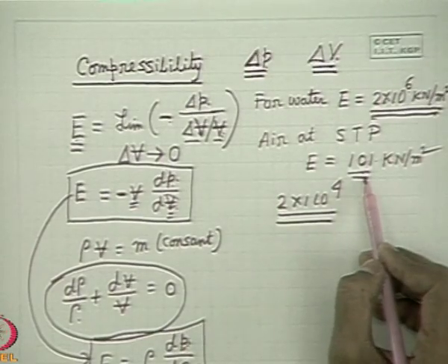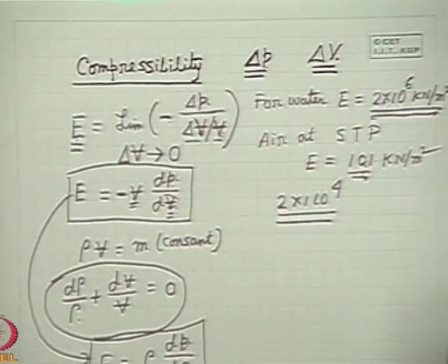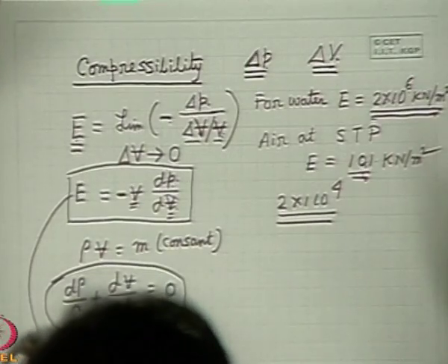So, the less the bulk modulus of elasticity, the more the compressibility of the substance. Well, it's clear. Now, a very interesting question comes in engineering applications. We define the fluid by the compressibility parameter, we apply the pressure and find the change of volume and density, and we find the value of the bulk modulus of elasticity. Qualitatively, we see that the change is very small even with a very high pressure, so it is less compressible, it is incompressible.